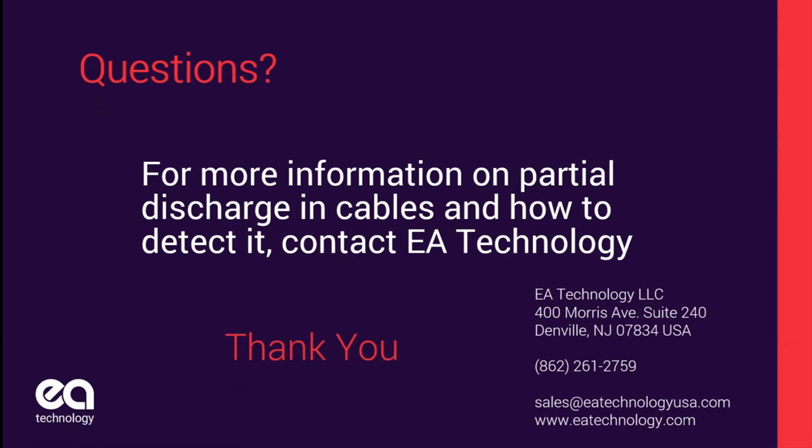On cables longer than the length limitations, can you confirm the RFCTs are still effective to see into the cable up to the limitation? As with everything in the PD world, there are no hard and fast numbers. Just because the cable's longer doesn't mean you won't see PD that might occur. It just means if it's past the point where you'd see it, you're not going to see it. But if it's within that first few kilometers, yes, you will definitely see it.